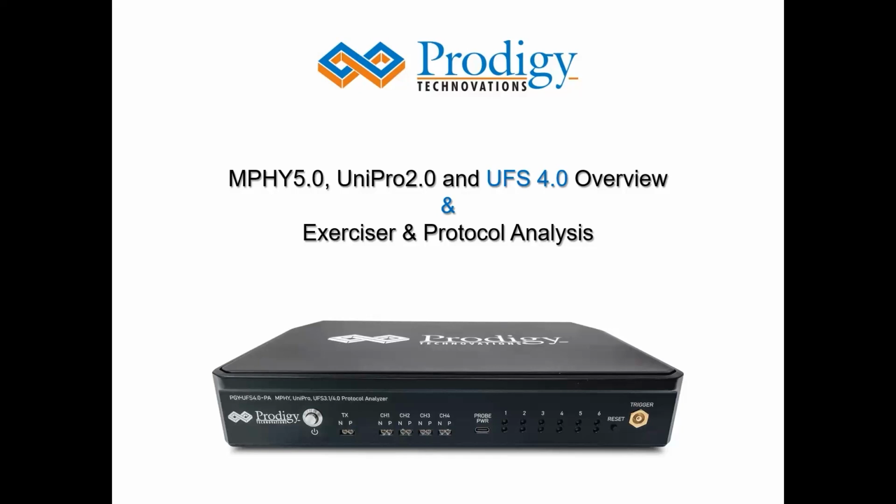When it comes to UniPro 2.0, in UniPro 1.8 the DL data payload maximum was around 276 symbols. But in UniPro 2.0, the payload has become a jumbo and it can go up to approximately 1,138 symbols. And then on top of it, you have the UFS 4.0 protocol. So that's the overview.